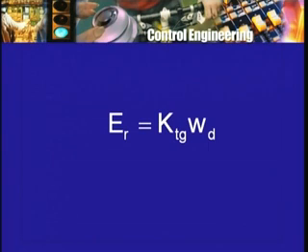But then I said that you cannot increase Ka by any amount that you like, because this is only for steady state error consideration. We have not looked at transient error at all, and we will see very soon that increasing Ka will cause some trouble for the transient performance. But we don't really have to do that. We just have to choose an appropriate E reference, ER, or alternately choose an appropriate tacho generator or take an appropriate part of the tachogenerator voltage for feedback, and the drive will operate at the correct speed.